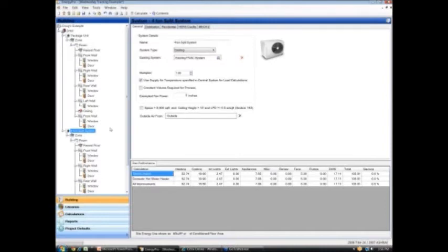If you have two units and they're both identical units, I could just say that I have this package unit right here, and I've got two of them. And I wouldn't even have this here. Then I wouldn't need to split my house up. Sometimes you can model this very explicitly and divide it up by these two package units. And it's not going to make any difference in my calculations as if I do the whole house and say it's being served by those two units.